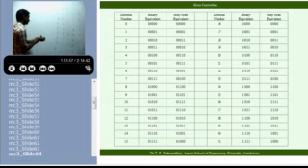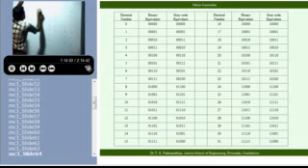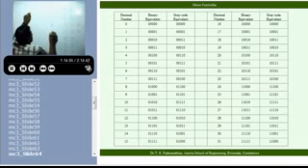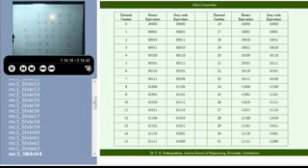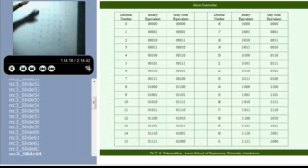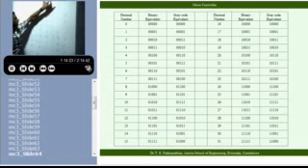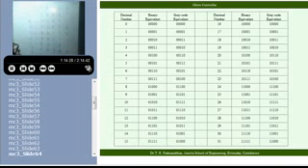It goes like this. 1 is represented by the combination, 2 is represented like this, 3, 4, 5, this is another representation of decimal number. In this representation, you can see from this bit combination to this, there's only one bit that changes. At every stage, only one bit will change. From here to here, there's only one bit change. From here to here, there's only one bit change.